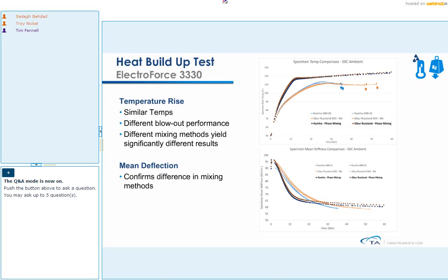So we all know that the amount of filler is dictated by the economy of the product, right? The filler is much cheaper than the polymer, so it governs the economics of the compounding, but it's the filler dispersion that controls the quality of the end product made from that compound. So in order to get the beneficial influence of that filler, you would want to make sure that carbon black is sufficiently dispersed.